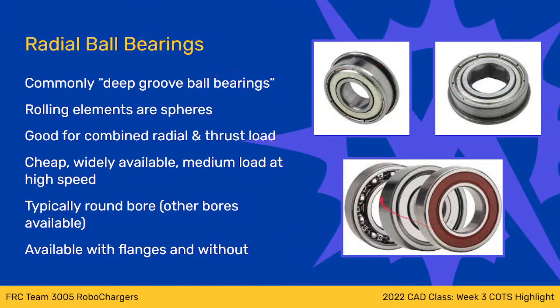There's a couple features of bearings. This little graphic down here is really great to emphasize. There's basically three distinct types of bearings. There's what's called open, which is where the sides of the bearing are open, and those can run very fast. They keep themselves cool because air can get in the bearing. So typically the highest speed rating bearings are going to be open. This next type in the middle is called shielded. These top two are also shielded. It's basically just got this metal cover over the side. The metal cover does not seal the bearing, but it keeps dust out.